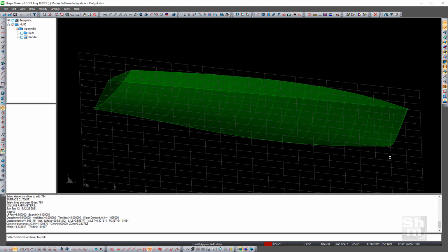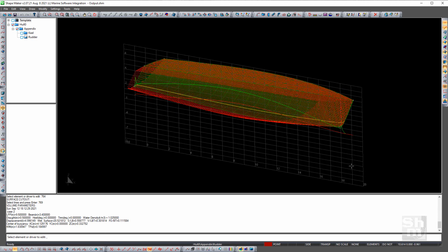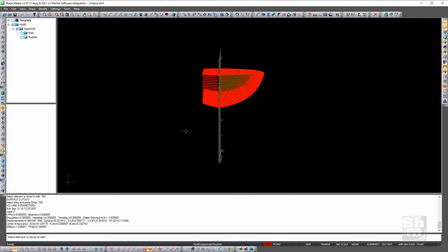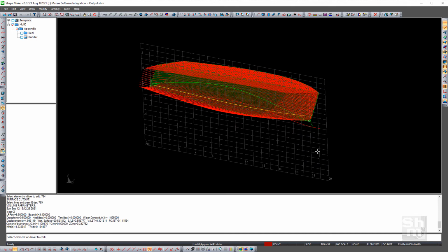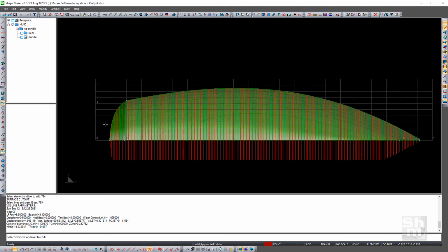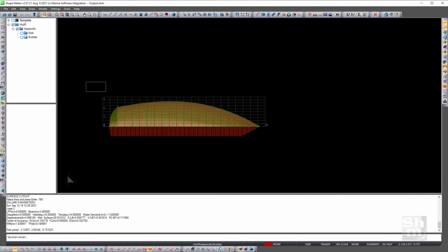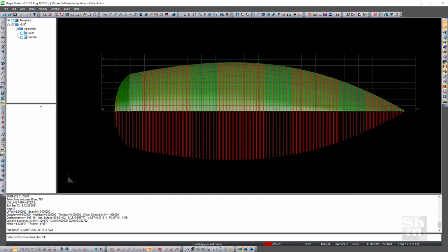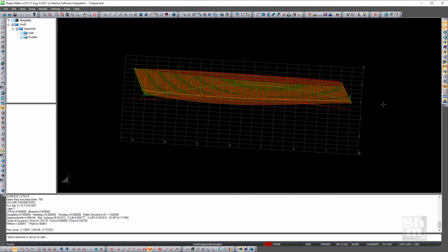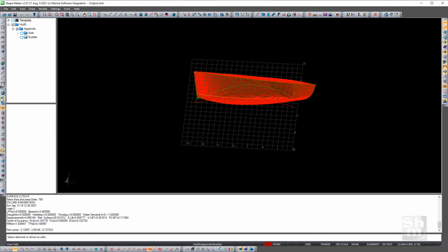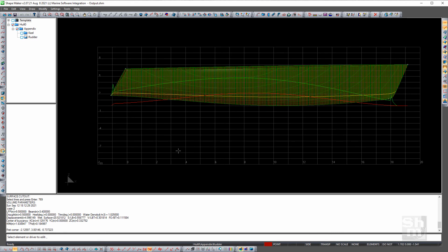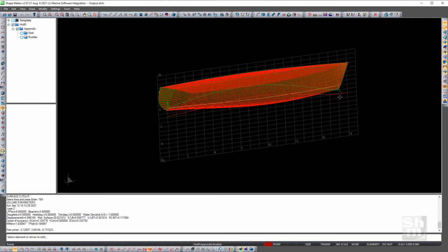In ShapeMaker, you can visualize the frames you use for calculations. For correct volume calculations, each frame should start from the center line and stop at the center line. So, for us it's important to close the volume with the deck surface. In addition to frames, you can see some lines, like the section area curve and some others.